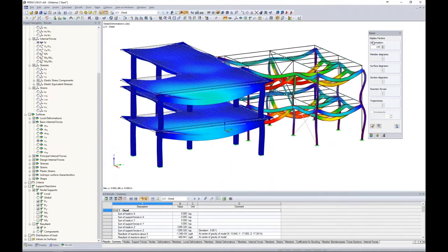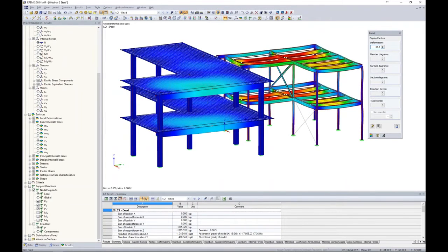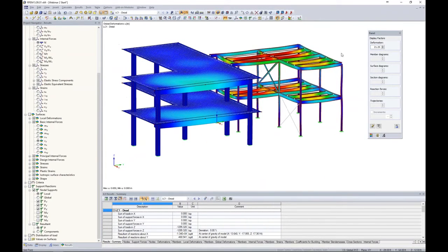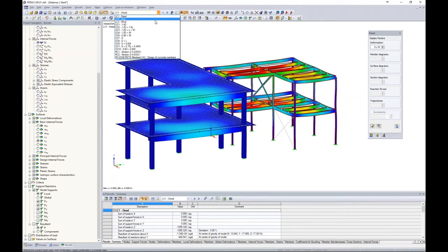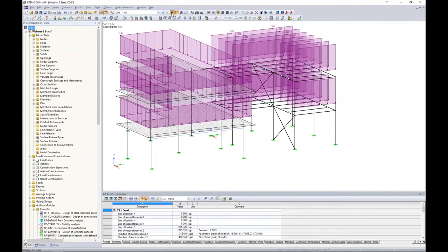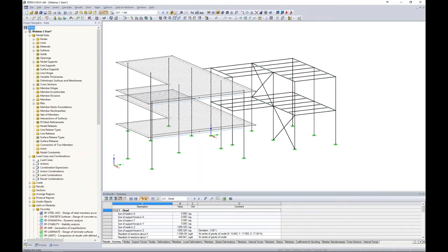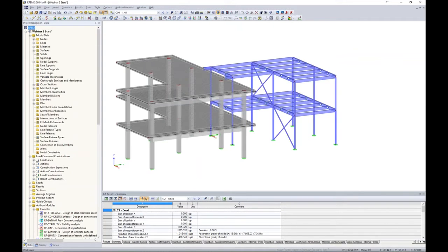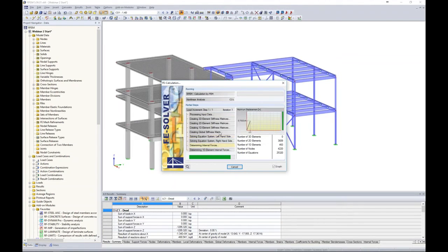We immediately get our deflections here, which we can decrease the deformation factor. So that's great, but now we need to run our first load combination, 1.4 dead load. So this is just a load combination from the ASCE 7. I take a look at my applied loads. It's applying that 1.4 factor to all of my dead loads, our surface loads and line loads here. And maybe turning this back into the rendered view, I begin my first load combination analysis.